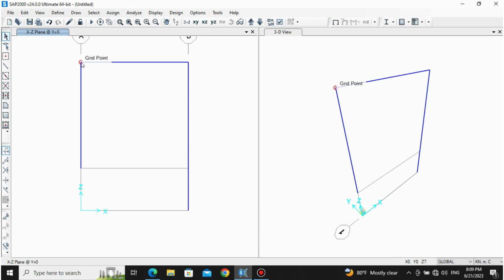So we have to keep continuous over here, because it means that it is a rigid support over here, not pin. If we keep pinned, it's like a hinge, so it is not going to transfer the moments. So considering continuous means like we are welding this joint, so making it fixed.